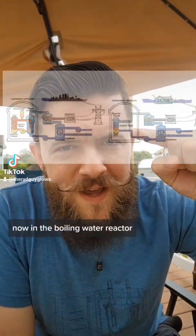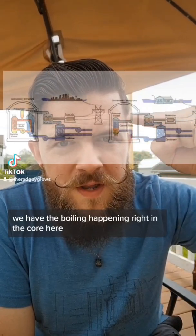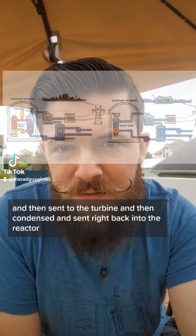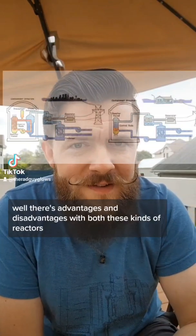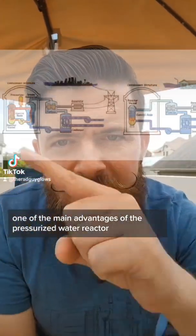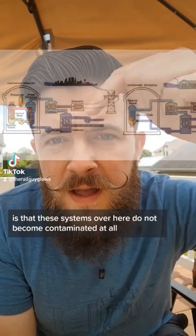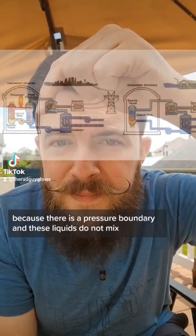Now, in the boiling water reactor, we have the boiling happening right in the core here and then sent to the turbine and then condensed and sent right back into the reactor. So why have the two different types? Well, there are advantages and disadvantages with both these kinds of reactors. One of the main advantages of the pressurized water reactor is that these systems over here do not become contaminated at all because there's a pressure boundary and these liquids do not mix.